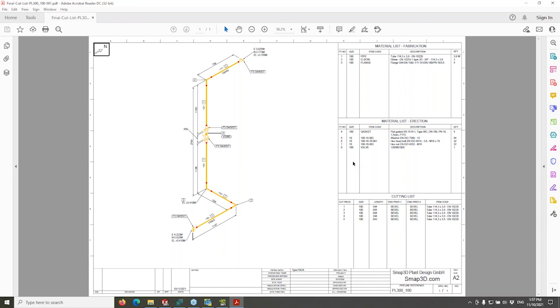Awesome, thanks. And I have another question, and it is, can we use your isometric drawing tool with SolidWorks routing? Okay, that's actually a very common question that I get from a lot of people that already have 3D done with SolidWorks routing, but they need isometric drawings. And the answer to that, unfortunately, is no, because SolidWorks routing doesn't have any ISO information, any Isogen information in it. So Isogen doesn't even know what it is, and so you'd have to manually program that for each pipe run. So you would have to redo the piping with our piping engine for isometric to be able to be used.